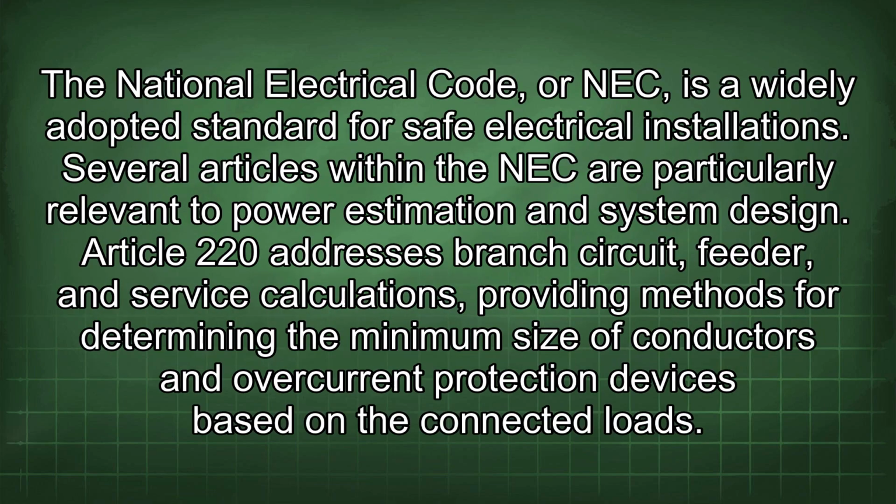The National Electrical Code, or NEC, is a widely adopted standard for safe electrical installations. Several articles within the NEC are particularly relevant to power estimation and system design. Article 220 addresses branch circuit, feeder, and service calculations, providing methods for determining the minimum size of conductors and overcurrent protection devices based on the connected loads.